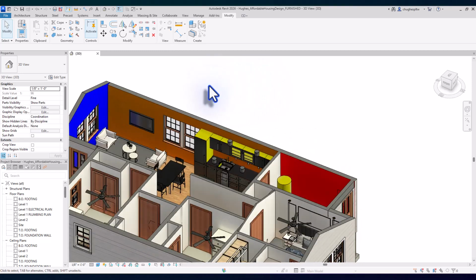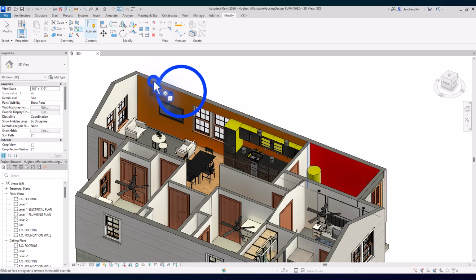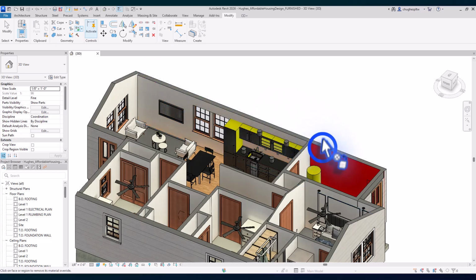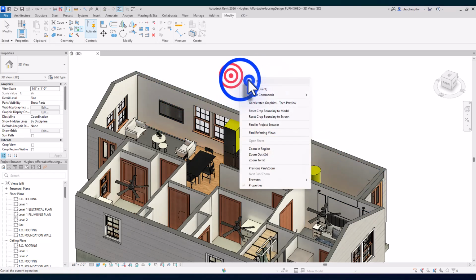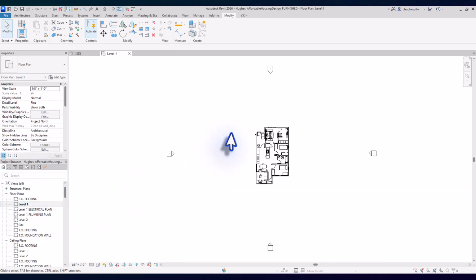All right. So again, that's just one of those things that you can do. Here's another option. If you don't like the paint, you can click the little drop down arrow. You can select Remove Paint. Select the walls, and it goes back to the regular gypsum wall color once it's highlighted. And there we go. Another really cool feature of using this Split Face option is that I'm going to go ahead and move to the level 1 floor plan.